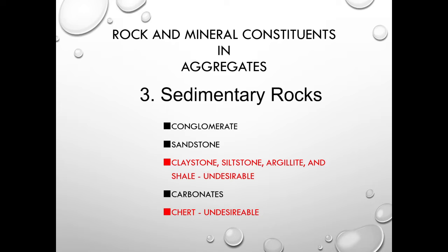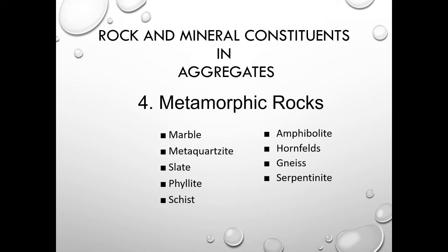If you're not too sure of your sources, you may want to do petrographic analysis to determine if you have some undesirable rock. Same with chert, very undesirable. These are referred to as low density aggregates, and they do not provide much durability in a concrete mix.